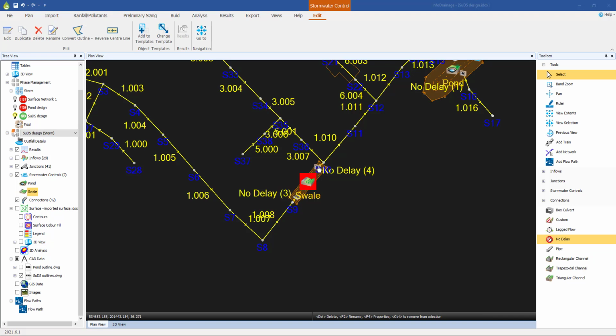And we've got to set the characteristics of the discharge orifice such that we utilize roughly 184 meters cubed of storage. Okay, so we did a similar exercise previously when we were designing the pond, but this time we're working in a slightly different way. With the pond, we knew the discharge rate and we were working out the volume of the pond. Here we know the volume and we're working backwards to calculate the discharge rate.